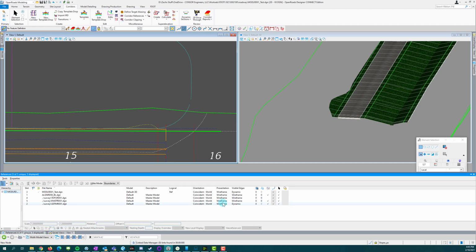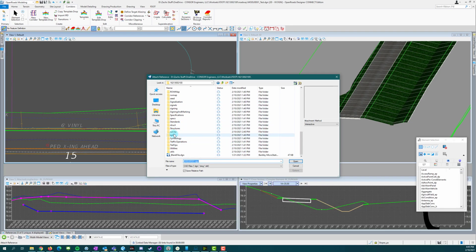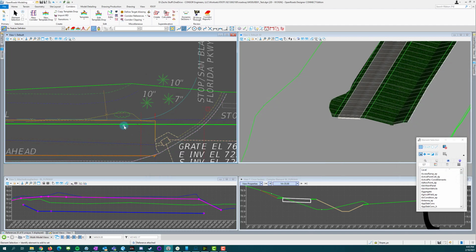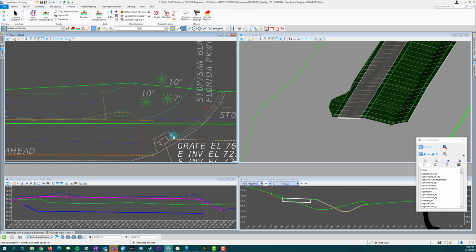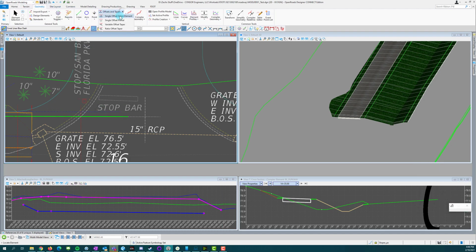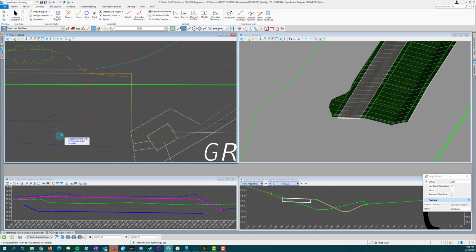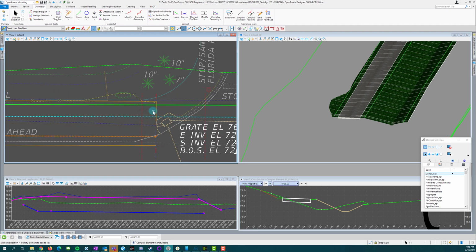And I know, looking at the topo and drainage existing in this spot, survey, drainage existing, we are more than likely going to have to try and get this sidewalk to go around this grate here. So this sidewalk might have to flare out a little bit as it approaches this right of way. So that's another thing we have to consider, is we probably don't want to impact this if we can help it. So just get an idea of where our front of sidewalk is going to be. Our front of sidewalk is going to be a 5-foot offset. So right now that front of sidewalk is clipping that a little bit. So that's going to be a challenge right there to avoid that, where you might have to flare out another 2 feet to get around this piece here.